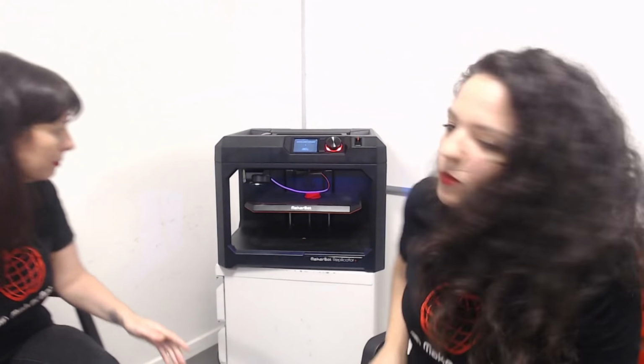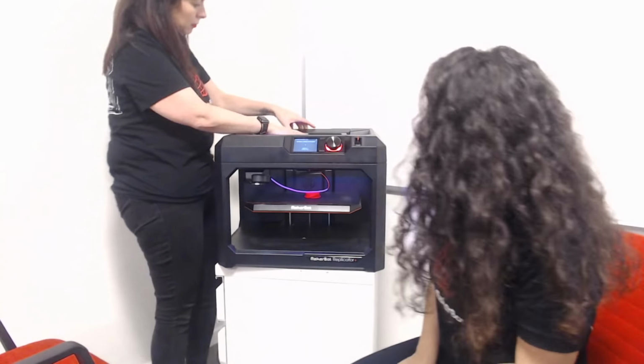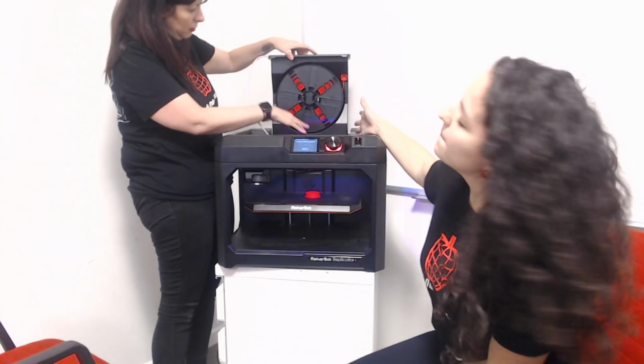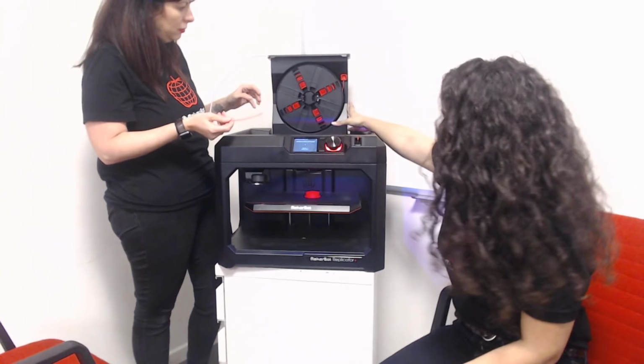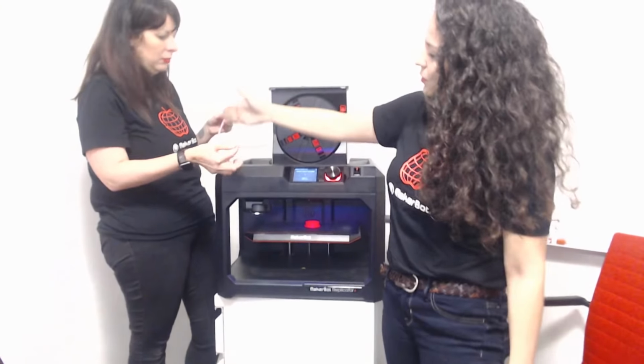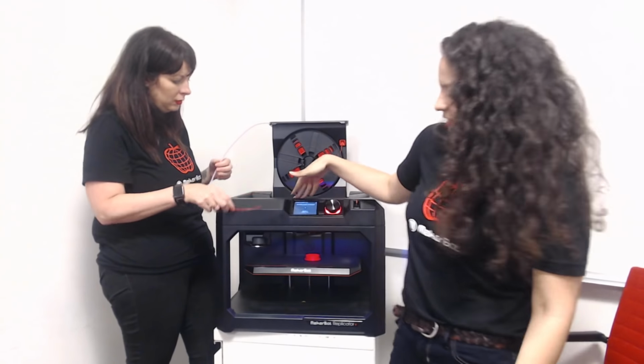Absolutely. So we're still waiting for the extruder to heat up a bit. It needs to heat up to 215 degrees Celsius. It is quite hot, so it takes a little bit to heat up. And you can see where the filament is actually stored. This is our filament drawer, and then the filament's routed all the way up through here, and then out. Currently we're at 165 degrees, so it's going to be just a little bit longer.